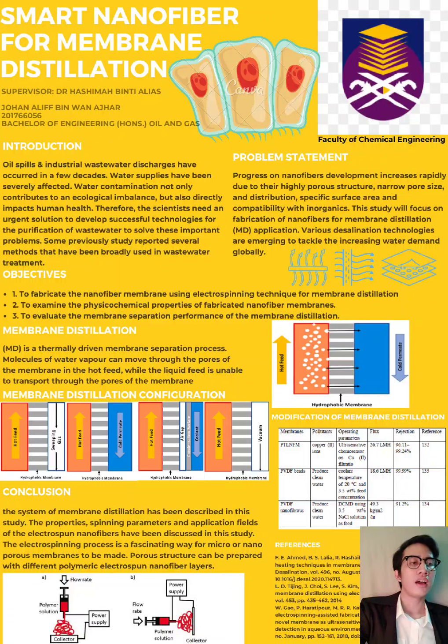They may build highly porous mesh networks with great interconnectivity between their pores, making them an appealing candidate for a variety of advanced applications. Membrane distillation is one of the most promising fields of application for electrospun membranes. For further medium-term development, the porous structure, hydrophobicity, and membrane performance are crucial. This review shows that nanofiber layers could be used in membrane distillation.